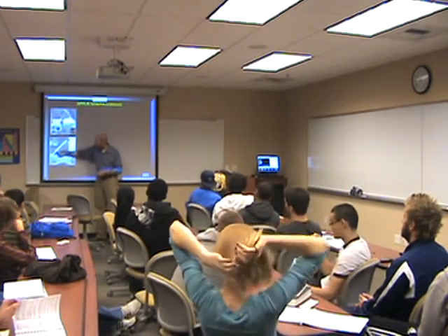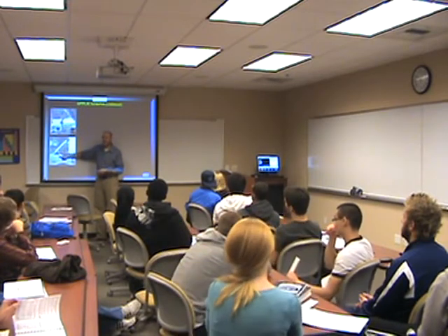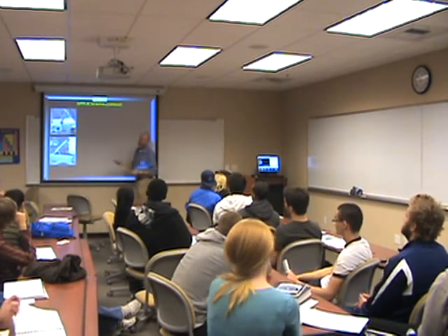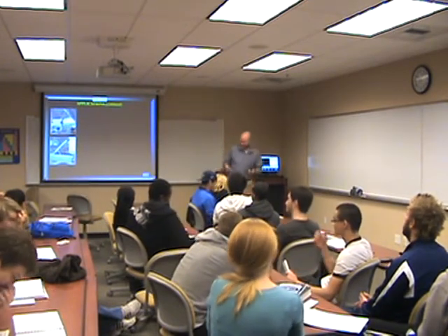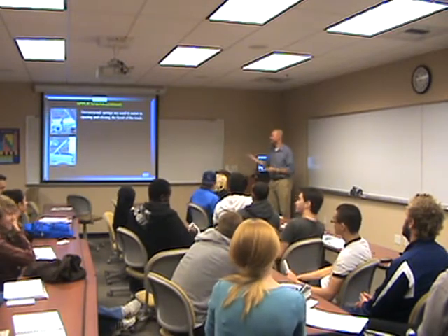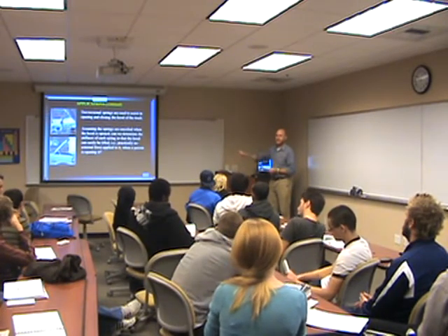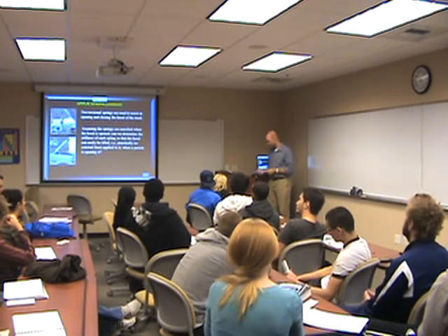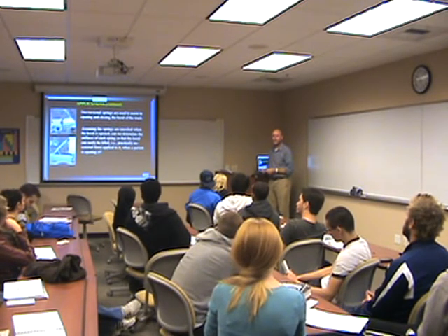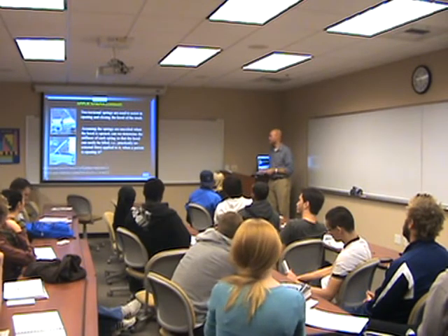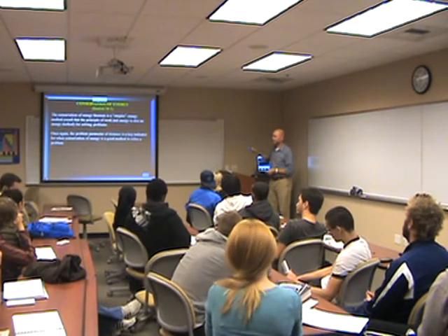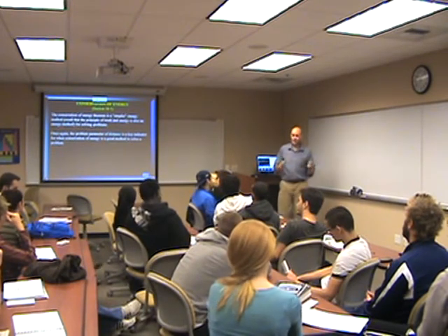And here we have a linkage, and so we can have our kinematic equation to relate the position change. We could if we were designing it, but we're not going to be designing it in this course. But that would be how they would design it. You would have your kinematics, so you can figure out the height of your car hood versus the angle between the two lengths. You develop an equation for that, and then you can figure out what your spring constant had to do with that.